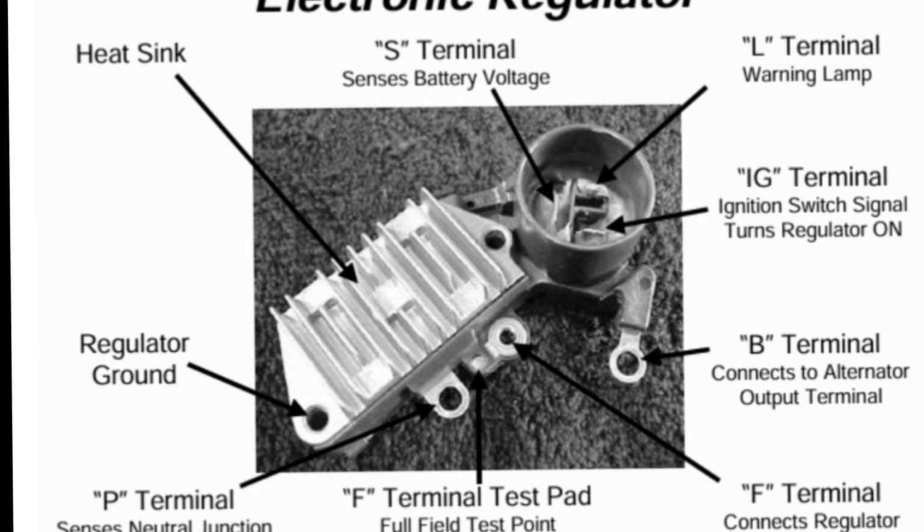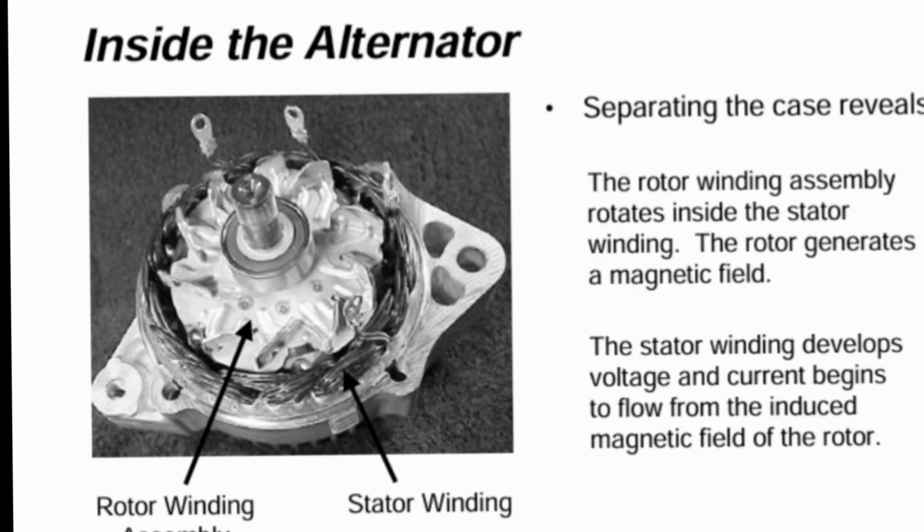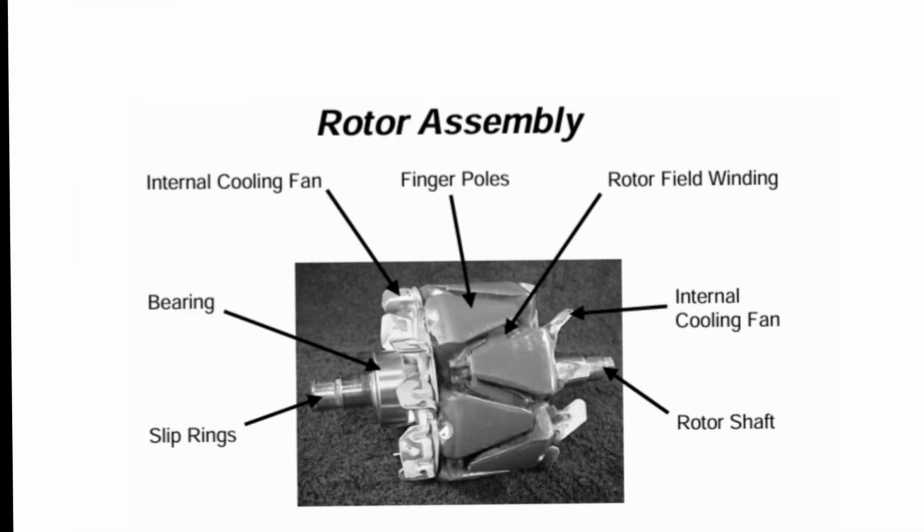Bearing check. Listen for abnormal noise. Belt tension. Loose belt causes low charging. Dust entry. Clean dirt and oil deposits. Wiring inspection. Check loose terminals and corrosion. Battery condition. Weak battery affects charging system.